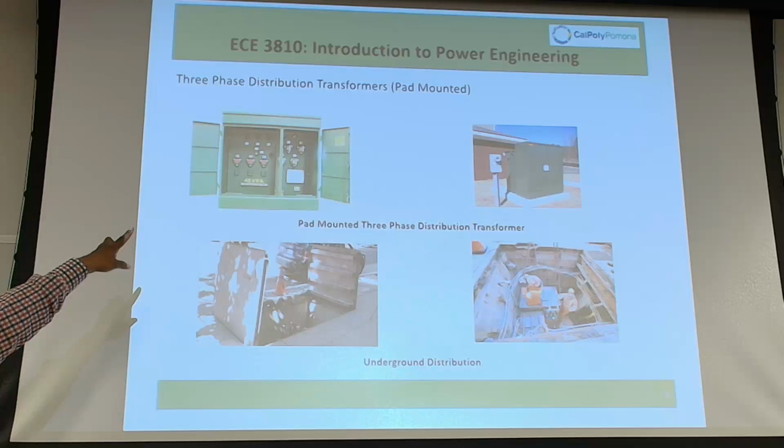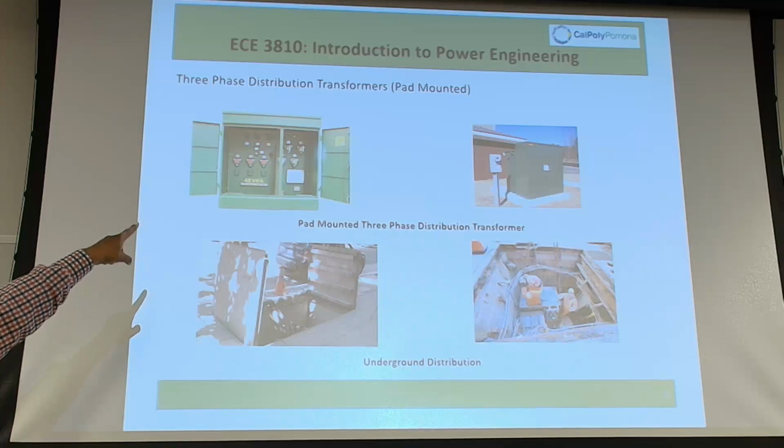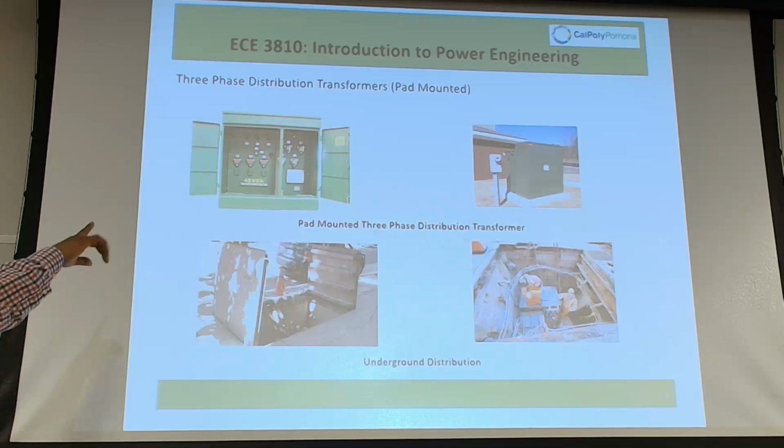That one is a smaller one, a 45 kVA, but the reason, once again, we call it dead front is because on the front of it, there are no live parts, okay? And you can see those red things that look like elbows, and that's where they connect the cables. The feeds are usually from the bottom, they're usually bottom feeds. So those cables obviously are buried. There's another one over there with a meter. So those are, once again, pad-mounted.